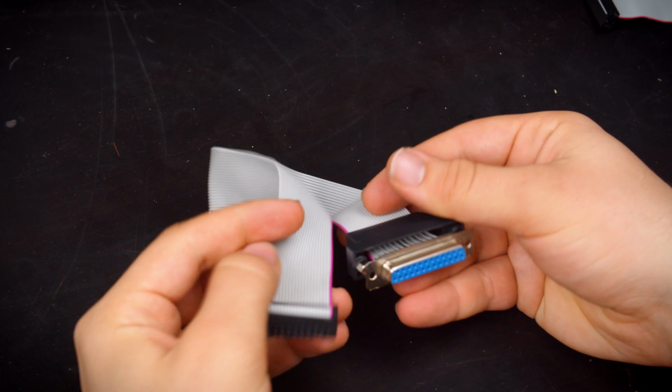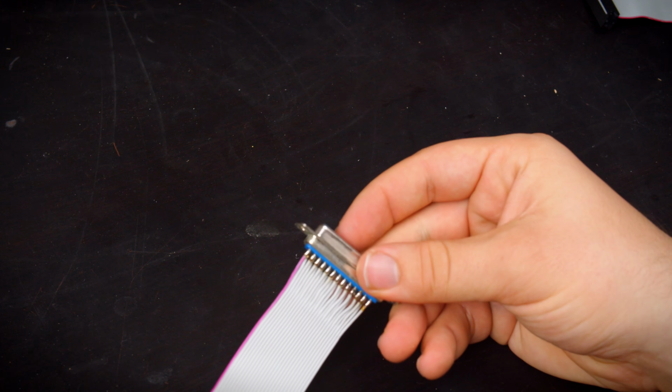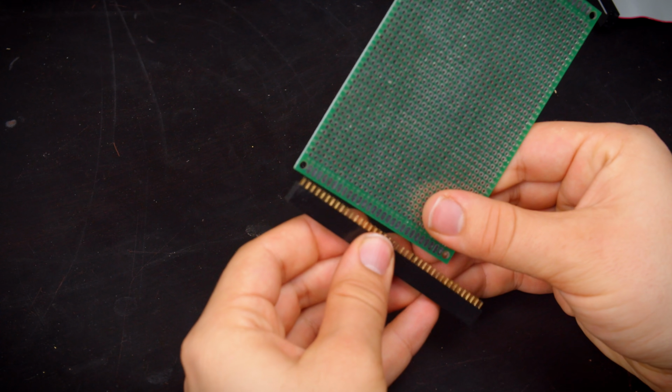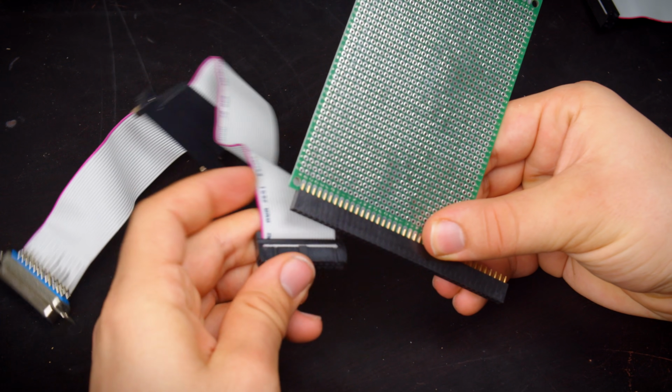Now, as a precaution, since I was aiming for an internal solution, I decided to measure all of my connections against a parallel port header cable. This also gave me the pinout of the motherboard header. Since I'd tested this with a printer beforehand, I knew that if I made my cable to match this, it would work. If you're making a D-sub cable version, you can just use the schematic as a reference point because you're not going to have that problem.